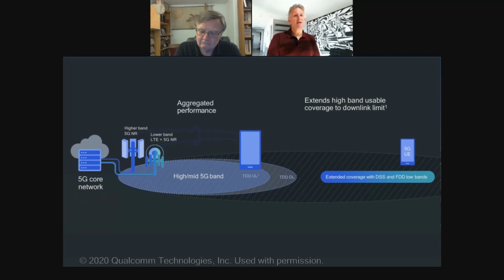So now comes the highest of the high band of the 5G, which has the least range, but man, it has got killer throughput and it has got fantastic latency. The good thing about that is that I can create these small cell zones with very, very small distances, and I can pack them in next to each other. So I can get high density. That's where we get 1 million devices per square kilometer.